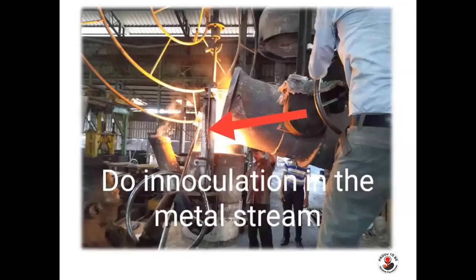Do inoculation in the metal stream. This is very important. How to do inoculation? You have to add the inoculation in the metal stream, and it should start after around 15 to 20% metal is tapped and finish when about 80 to 85% metal is tapped.